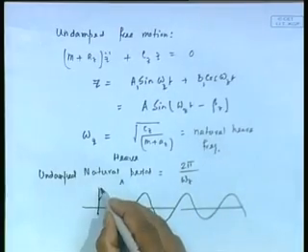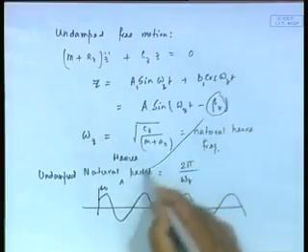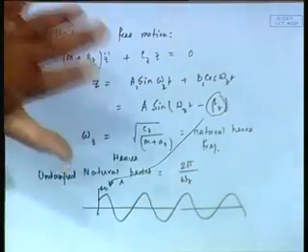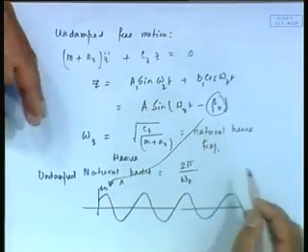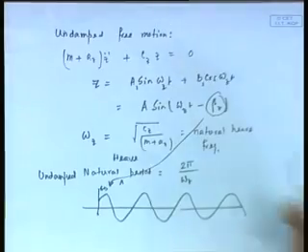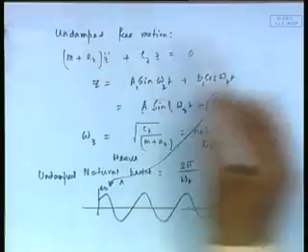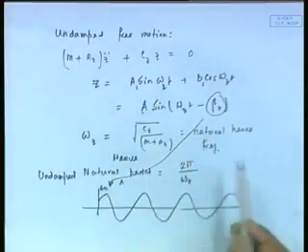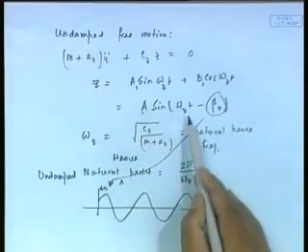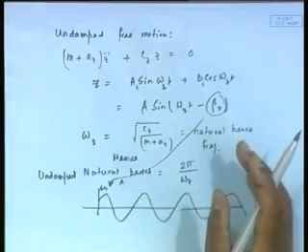Okay. The beta is going to be a measure of this, that is the phase. This beta measures in some sense how much later, with respect to t equal to 0, it is having a motion. Essentially, if I know A and if I know beta z, then the solution is fully complete. In this equation, of course, I am assuming we know m, az, cz. So if I know omega z, the only unknowns are A and beta z, and of course I can always solve it if I have 2 initial conditions, but that is a trivial thing, not very important.